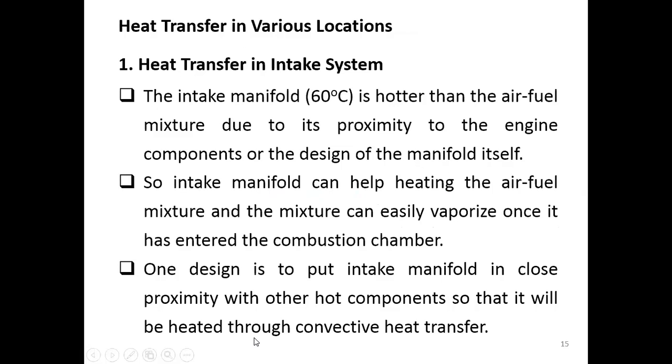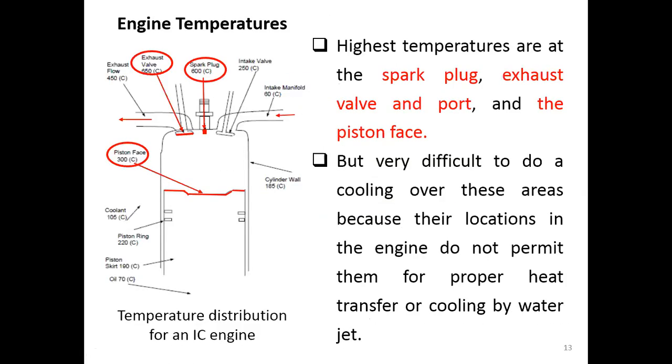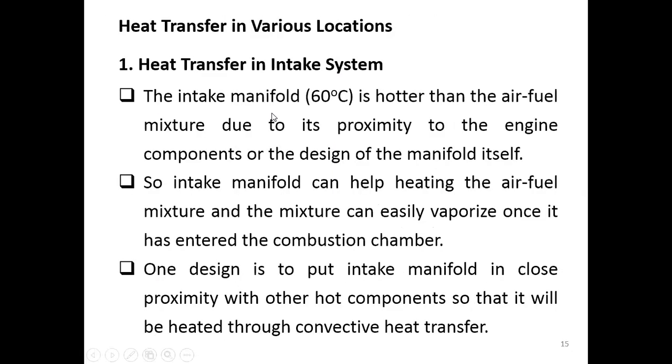So look at the heat transfer in various locations. Look at the intake system. The intake manifold shows about 60 degrees Celsius in this picture, which is of course higher than the air fuel mixture temperature. It's hotter than the air fuel mixture. Why does the intake manifold have this high temperature?